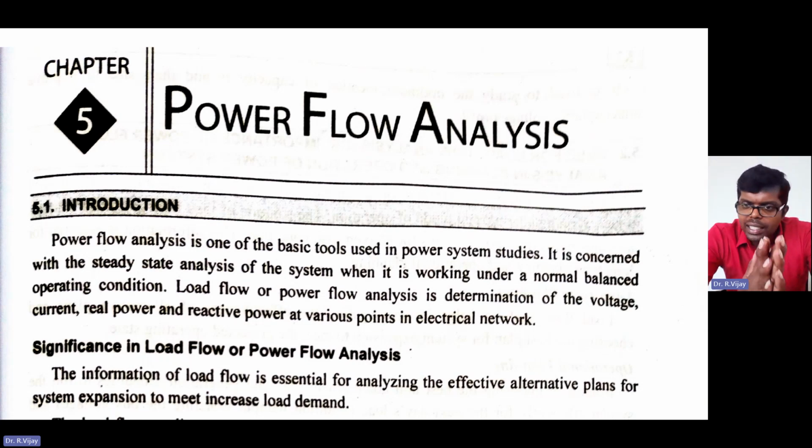At the generator bus, what are these values? At the transmission bus, what are the values? At the load bus, what is the value? We need to determine them at various points in the electric network so that we can understand whether the power flow is happening correctly or not, and whether it is working under normal balanced operating conditions or whether there are any losses. Many things we can find out by using this power flow analysis or load flow analysis.